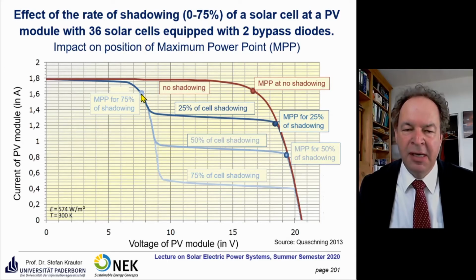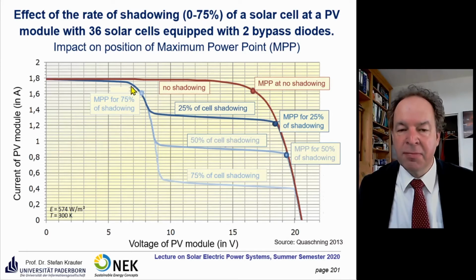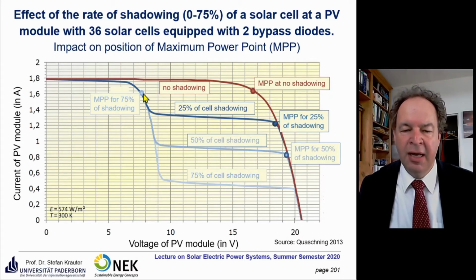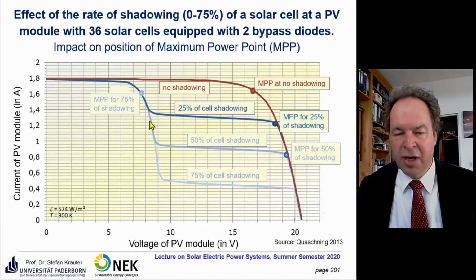Only if you do a full swing along the full range of voltages will you find that maximum power point. So this really depends on the algorithm or strategy of the maximum power point tracker, whether it just does a differential tracking, or whether it does a full tracking over the full voltage range. Sure, it takes longer to do that because you have to carry out all the multiplications to find whether the power is increasing or decreasing. But in the end, you have the best results.